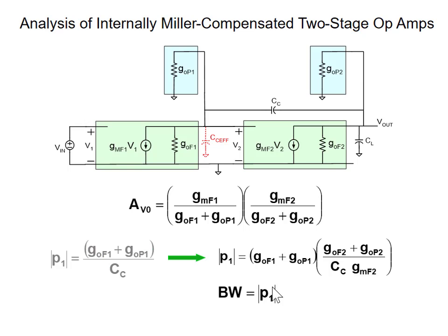This is our pole before. Right? Well, this pole is a low frequency pole. So at low frequencies, we can neglect the high frequency pole, so I can neglect what's happening out here. And this capacitor at low frequencies looks like C sub C times the gain. Right? At low frequencies, this capacitor looks like C sub C times the gain.